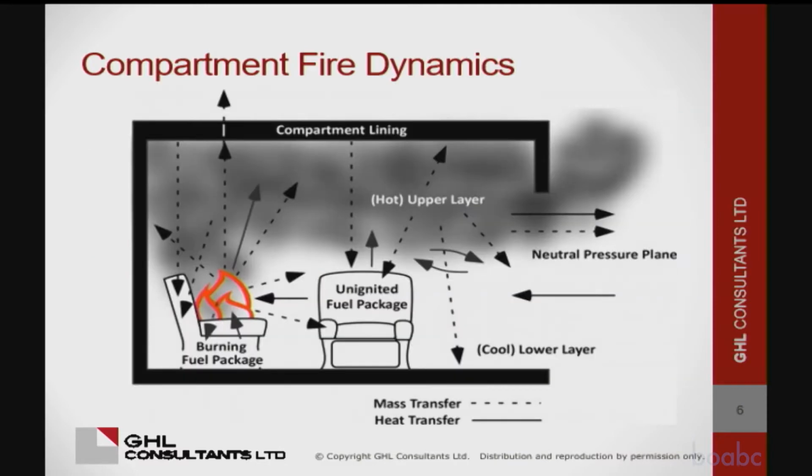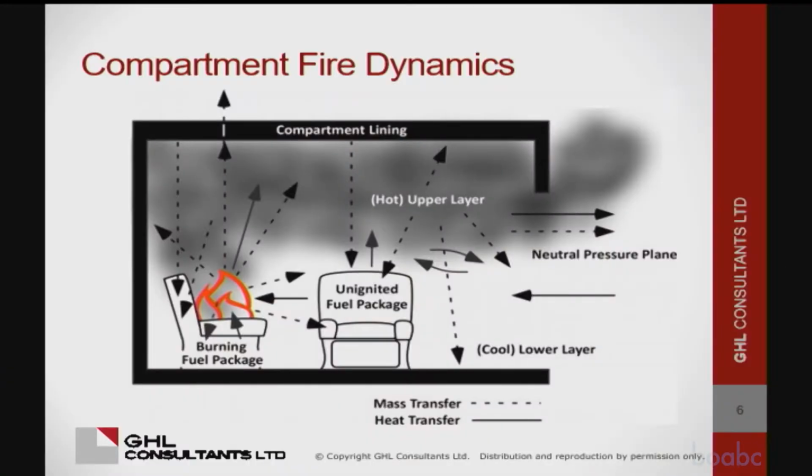So I'm just going to start out with the very, very basic stuff. Some of this you've seen a million times, but just the concept of what a fire compartment is, what a fire separation is. But then what I really want to do is get into discussion about closing the holes, because that's where everybody gets all hung up. So a fire compartment is basically a box, and the fire starts up there, and the heat rises, and then it starts radiating back on itself as the surfaces get hot, and eventually everything goes at once.